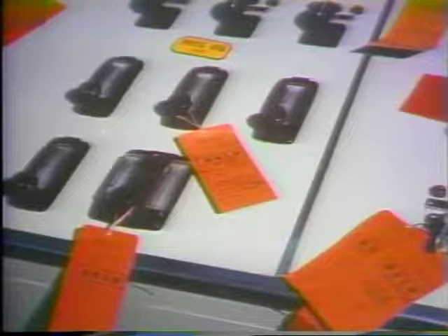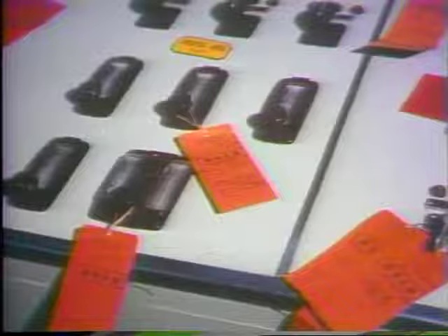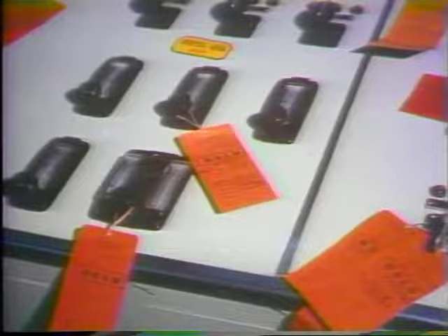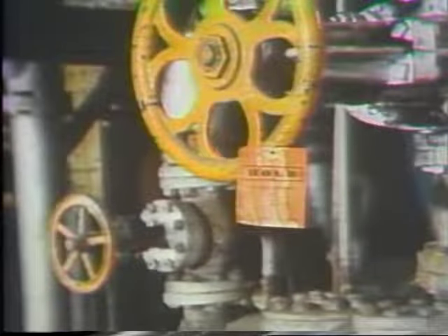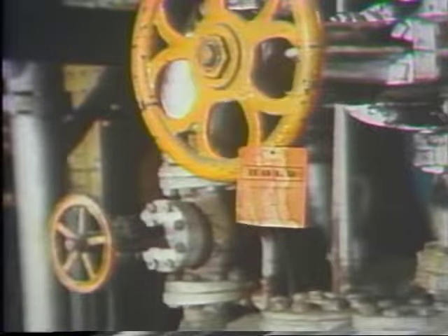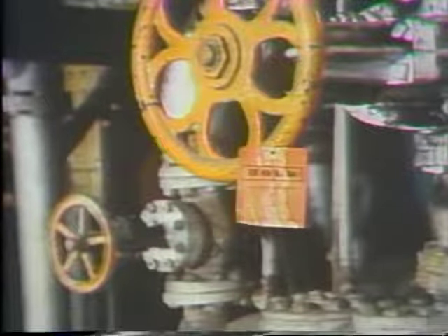Basically, when a system is tagged out, the operator places a color-coded tag on the components that isolate the equipment which is to be worked on. That is, tags are put on all components that could create a hazard if they were operated while the maintenance crew is at work. A piece of equipment that is tagged for personal protection should never be operated until the tag has been removed according to plant procedures.